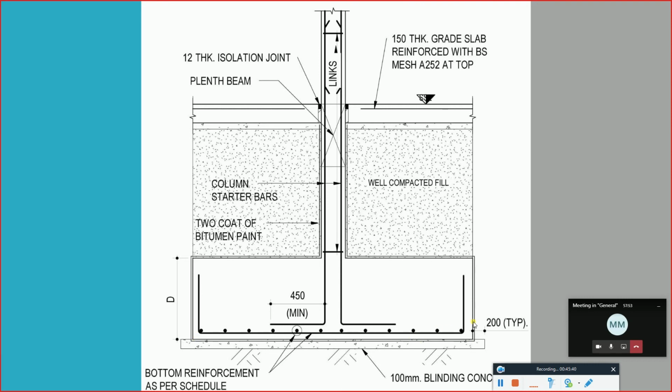The same thing goes for the other reinforcement. How are we going to calculate it? We are going to get the width. We are removing the cover from this side. We are removing the cover from the other side, and we'll calculate the length of the bar. How much is this particular portion? This particular portion once again is going to be the same thing. I need to get the depth, remove the top cover, remove the bottom cover. The remaining portion is considered to be my length of bar here.